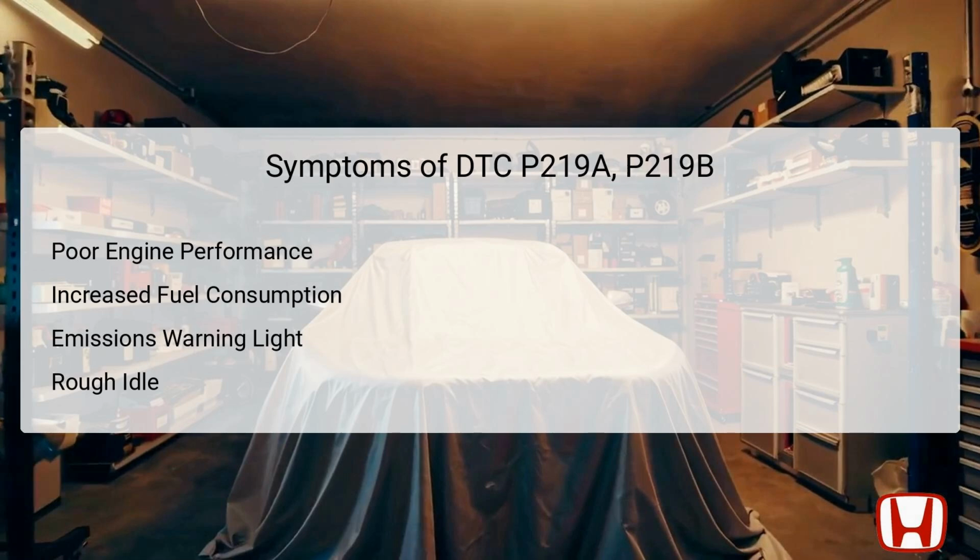Firstly, poor engine performance is a common sign where the vehicle struggles to accelerate adequately or operates sluggishly. Increased fuel consumption is often observed, as these air-fuel discrepancies may lead to a rich or lean mixture, driving the engine to use more fuel than necessary.